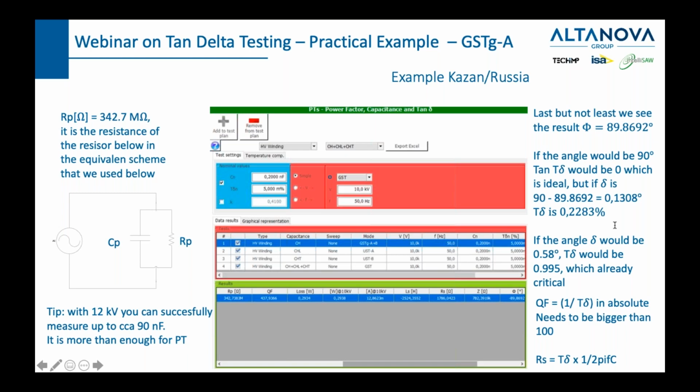So it can be bigger, it can be smaller, but until now we managed to test at least up to 100 to 200 meters of medium voltage cable. So the smaller the capacitance per kilometer, the longer the cable you will be able to test. In some cases, maybe you could also use the reactors, which are the devices usually used to test tan delta for generators and motors, and increase that to even bigger length.